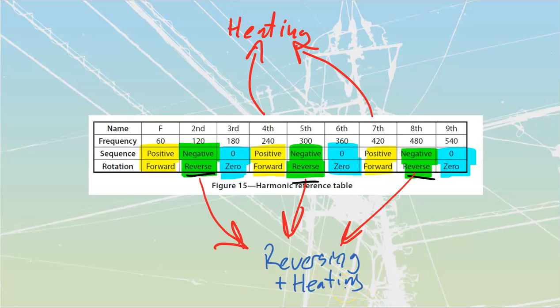And then the last ones, going back to these ones here, are going to come off of drives in a lot of cases, because we're going to have this switch down every time that we go through our 6-step drives, where we've got these voltages going on, then down, and back up, and then back up like that. That's going to be a 6-step drive over there. We're going to be collapsing these fields, and as we collapse these fields, we're driving current back through in the opposite direction, and any harmonics that come back off of it tend to add onto these ones. So our older 6-step drives were really, really bad for giving us these type of harmonics, the negative sequence harmonics.